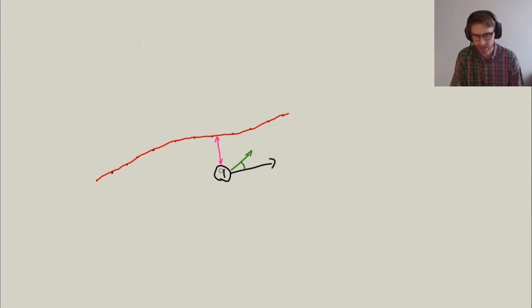So I can demonstrate that. So this is case 1. Let's say that instead the turtlebot would be this far, still heading that way. This is case 2. Now we have a cross-track error over here that is this big, which results in a much larger steering command, like this. Okay, so these are 2 different scenarios.